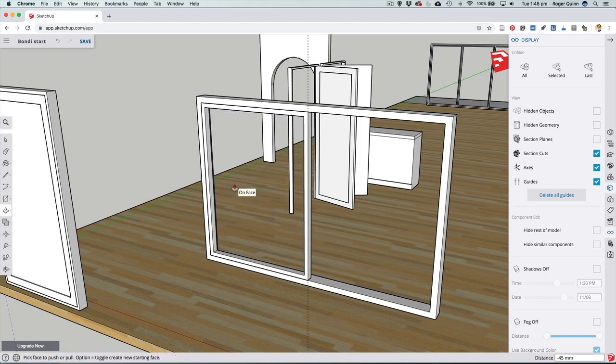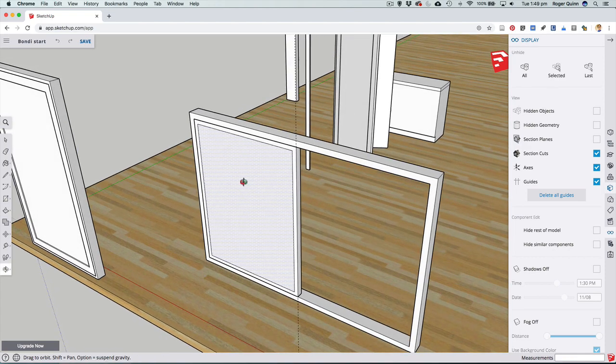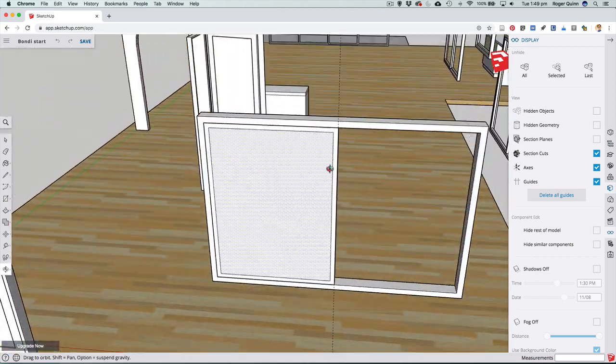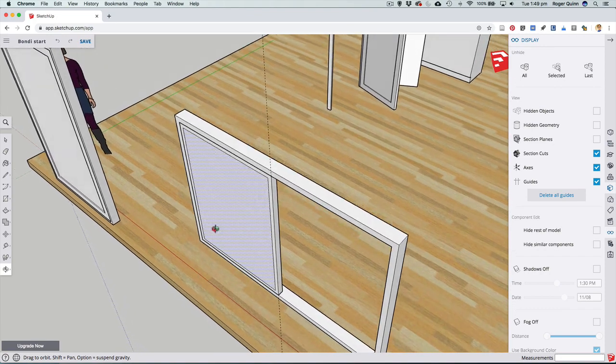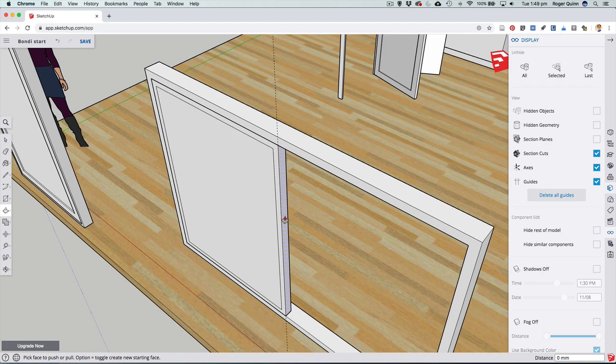And there it is. Now again, if you have any difficulty doing that, if it's playing up and won't cut the hole through, you might notice I'm using the orbit and the hand tool a lot so that I can get to the view that I need to see what I need to work with. So an alternate way to have knocked the hole through that is to push-pull. And then remember, you can come up here and, actually, in this case that won't work, come to think of it, because that's going to give me the thickness of the outer frame. All right, what I need to do is be able to see that thickness of the internal window.